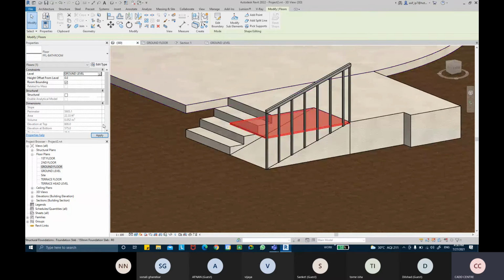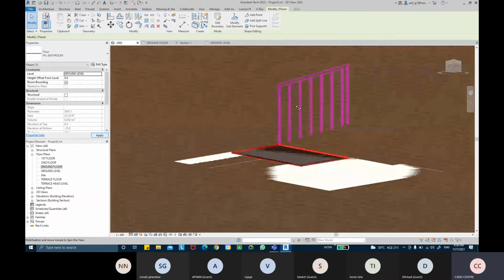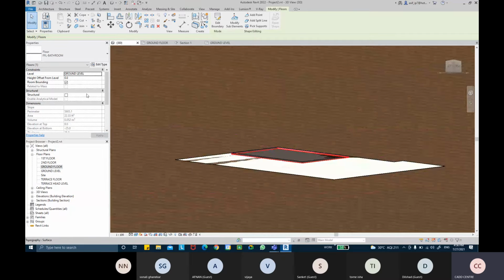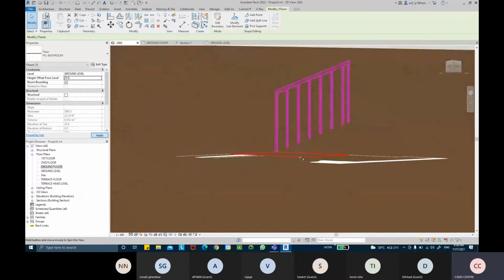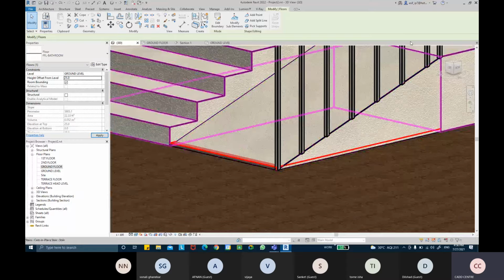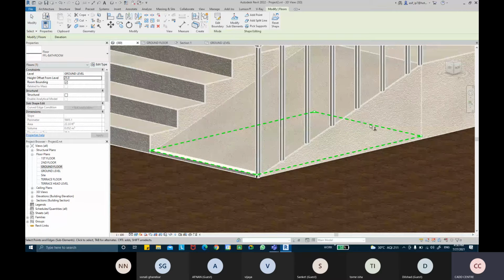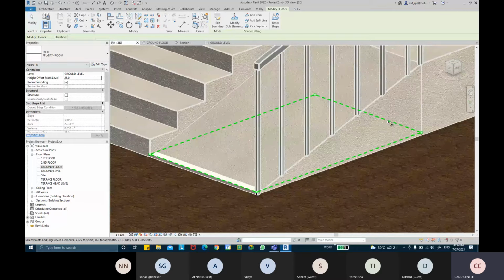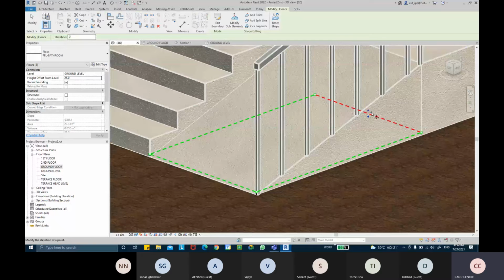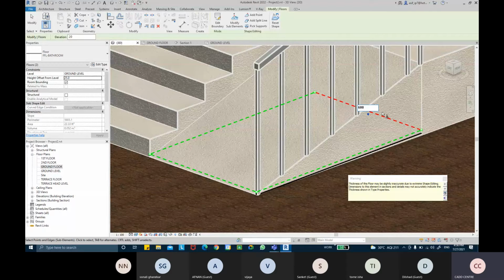I forgot about the level. The problem is that it goes below. So first of all, the height offset is 25 mm, so we raised it, but once again it's not inclined with that ramp part. So we'll take the modify sub element tool, and then we can select that line actually, and tell the line to go up to 600 mm.